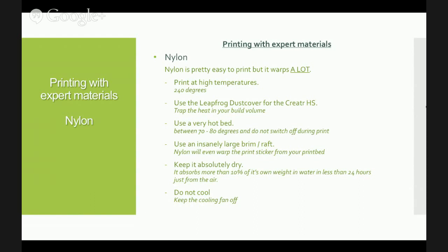So make sure that the nylon is kept in a sealed bag together with some silica gel. And if you expose your nylon again to the air and it has absorbed water, make sure that you bake it out in an oven. Do not cool. While printing nylon, you can keep the cooling fan off.